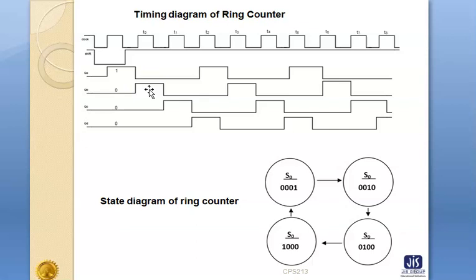Okay, as the 4-bit ring counter, that is 4 stages and 4 flip flops, circulates the preset digit within one clock signal, the output frequency of each flip flop is 1/4 of the main clock frequency.